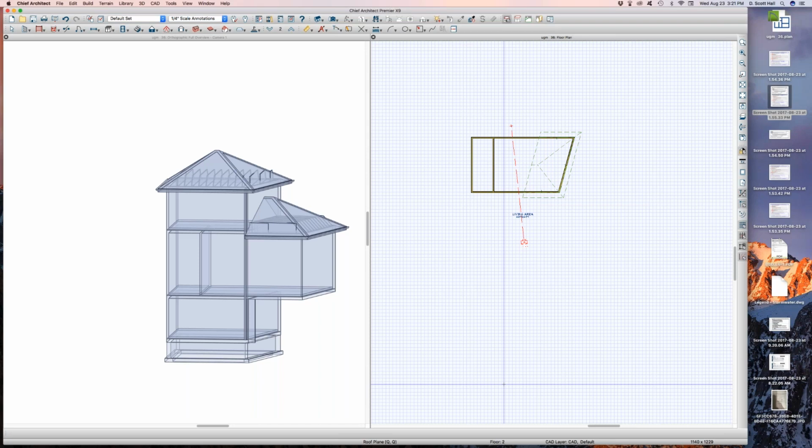And my question is, let's say you added a story or not a story. Let's say you changed the height of a story from 8 foot to 10 feet, just as an illustration. Would it automatically adjust whatever custom roof you had by that extra 2 foot? No. Okay. And that's what I was saying with the linkage, and I think Revit does that too, linkage of the connection between the roof and the wall.